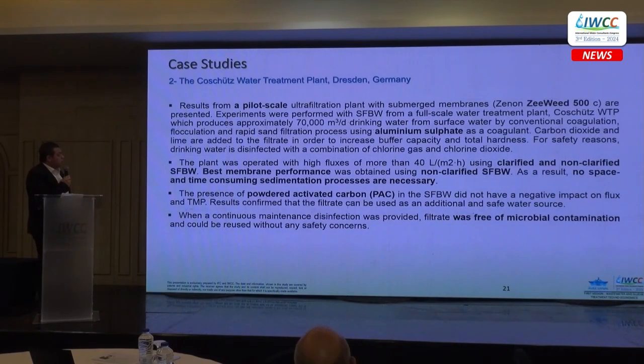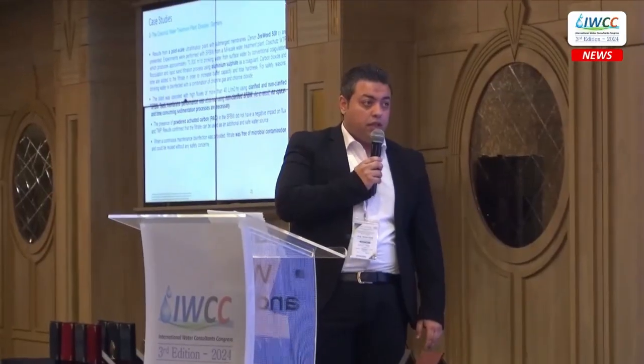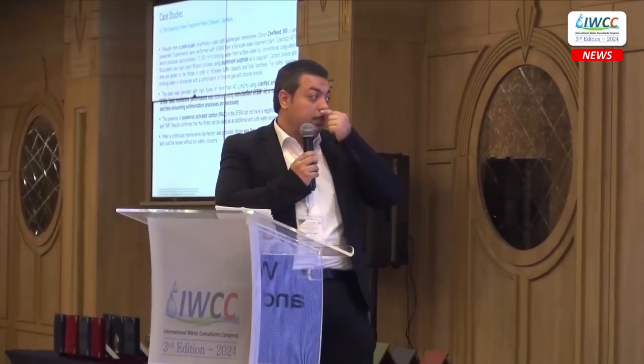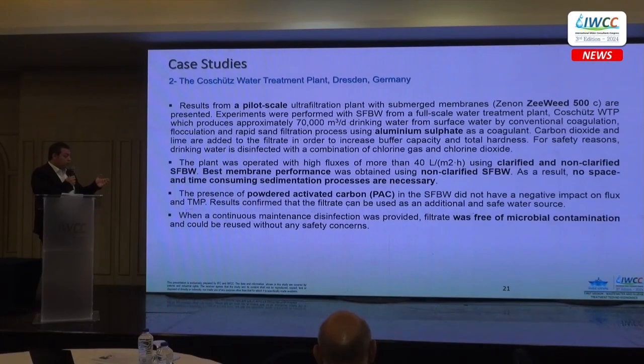The other case study was just a pilot scale in Germany. They used a submerged membrane, and they used clarified and non-clarified spent filter backwash water, and they concluded that non-clarified spent filter backwash water achieved the best performance. So you don't need to build a clarifier. They also used powder activated carbon, and it didn't affect the transmembrane pressure and flux.